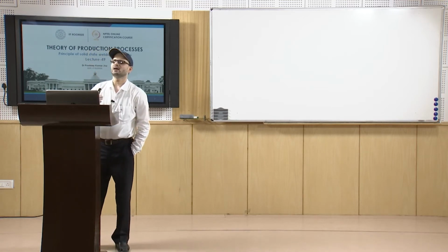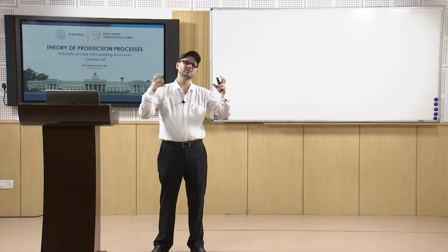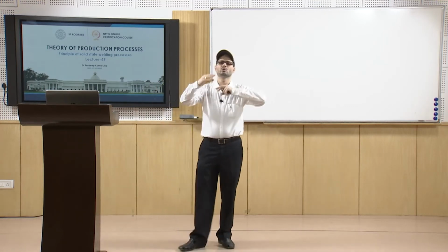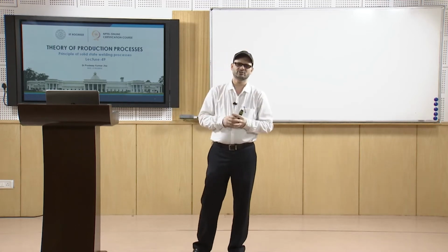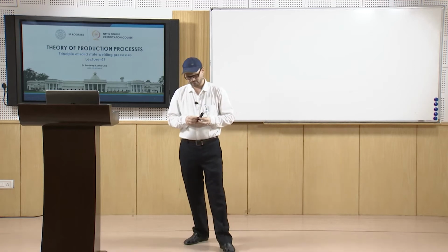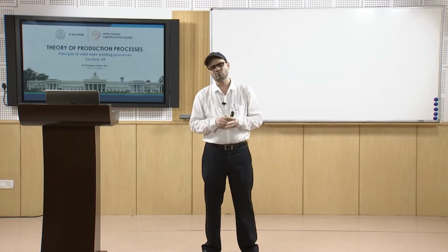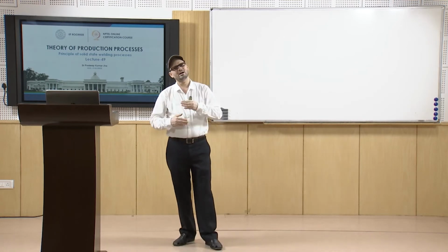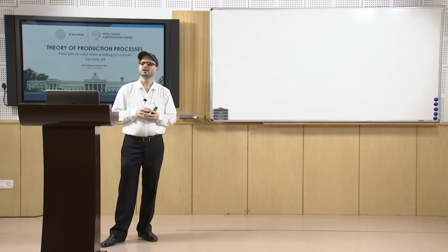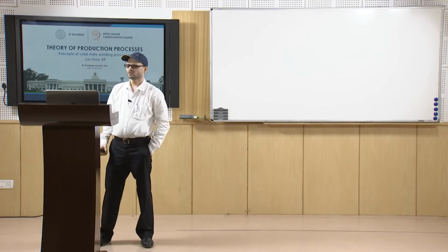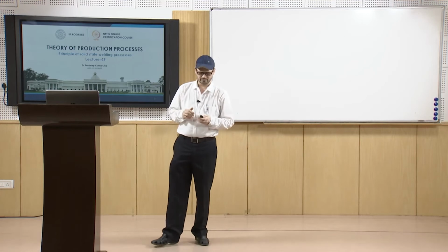The joint is basically similar to the ones produced by electrical resistance butt welding processes such as flash and upset welding, where you go to a certain state and then apply the pressure, and the joining process takes place. In resistance welding you apply current, so you must have a proper current source, and a large amount of current is required. Here that requirement is less. You need the current maybe only for the movement of the parts. So a good quality weld is produced in friction welding.